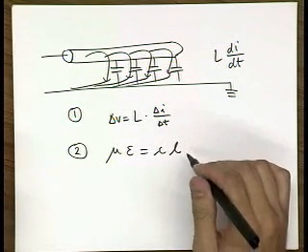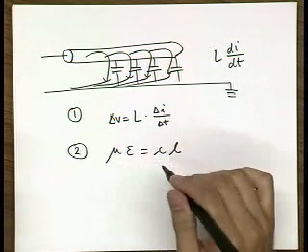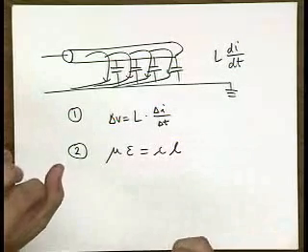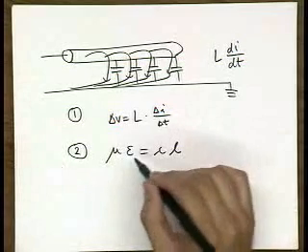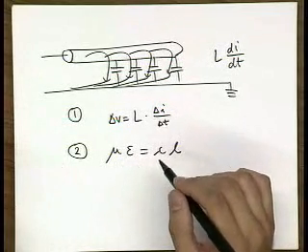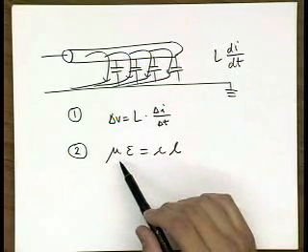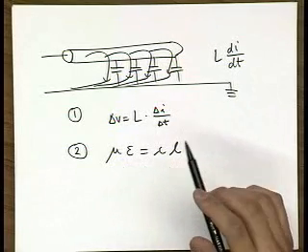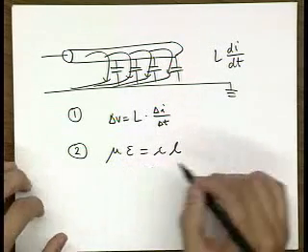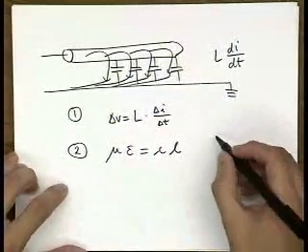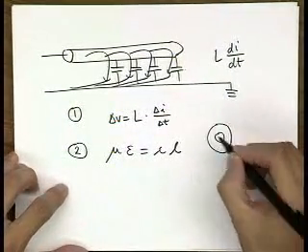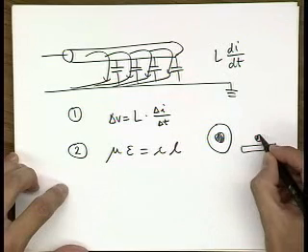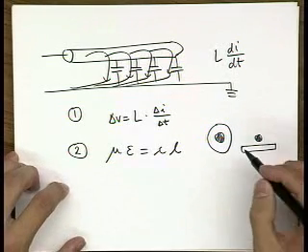Now we have to take this with caution, because this is really applicable to the case where you have a wire that is shielded with dielectric, surrounding dielectric. But then you can pretty much take average constants of dielectric, mu and epsilon, to make this analysis applicable, because it really gets complicated to analyze inductance when you don't have a scenario like this. For example, when you have coax or you have wire on top of ground plane and so on.